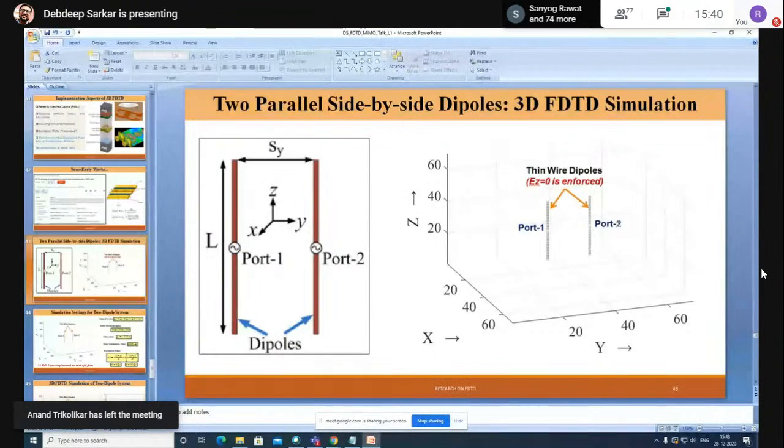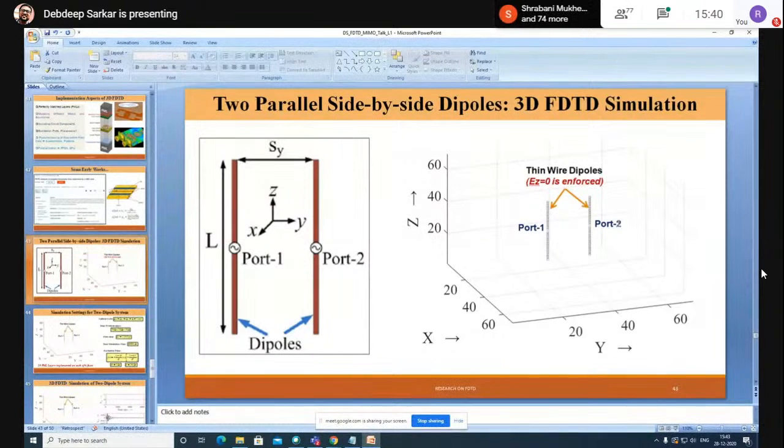In terms of master slave, I think it is better from the FEM point of view, or that kind of nomenclature is there in ANSYS HFSS. The idea is that we have to ensure the periodic boundary condition. So there are Bloch modes, Floquet modes, and kind of stuff like that to enforce this periodic boundary condition. Interested people can look into the corresponding literature.